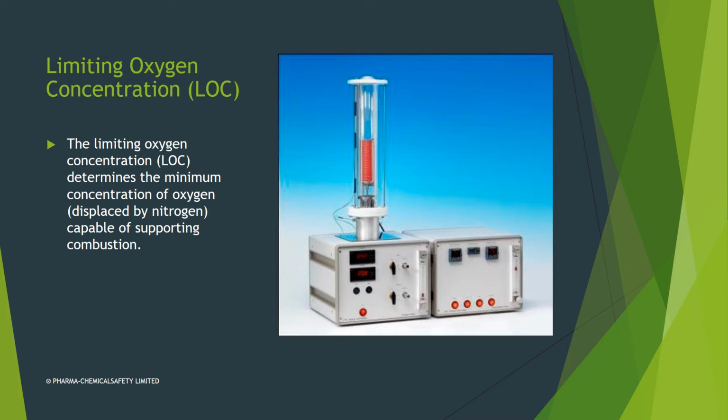Some of the ST2s or the ST1s, like powdered milk sugar. So the LOC is around 12%. That means if you're above 12% oxygen concentration in the tank or the mixing tank, now you're gonna have a potential. The likelihood to have a deflagration inside of that tank is gonna be higher.